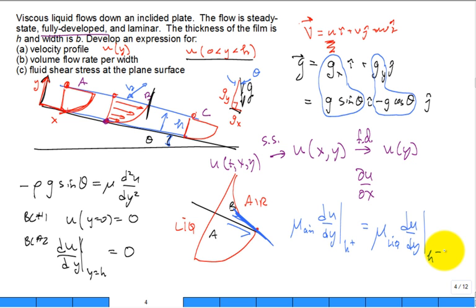Okay? But the viscosity of air is much, much smaller than the viscosity of liquids. Hence, we basically let this be 0, because of the small viscosity, even though you may have a dramatic change here, it's still approximately 0. There's a little bit of logic on that boundary condition. The air isn't retarding the flow of the liquid at the top.